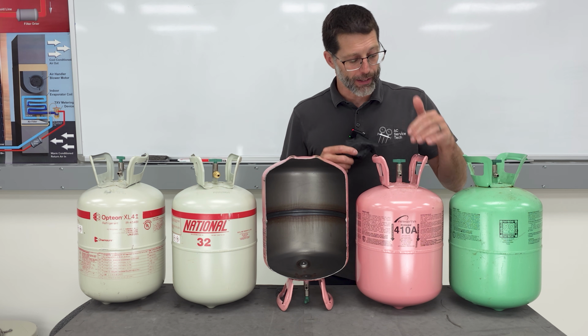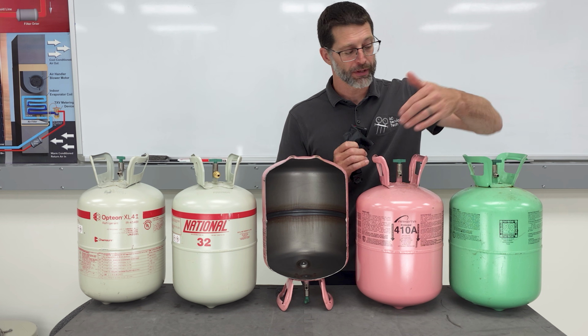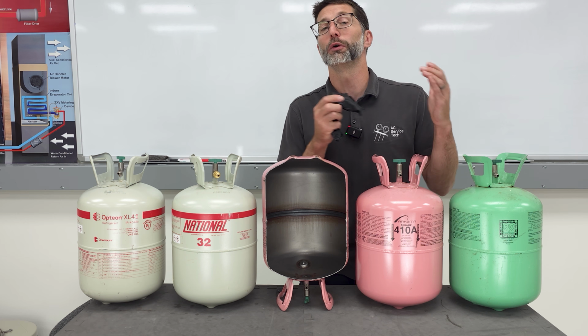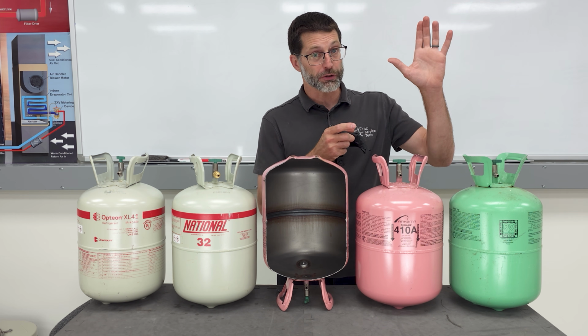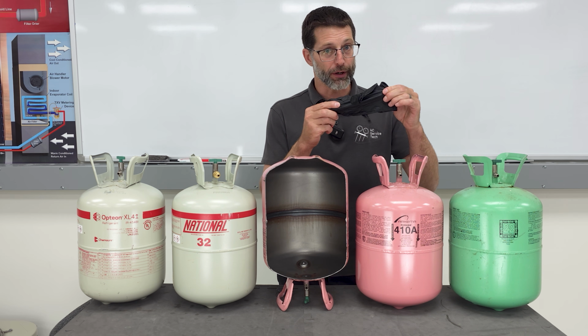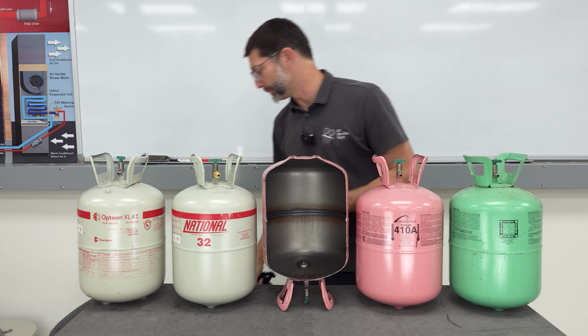As the refrigerant exits the bottle, you've got to think it's at a certain pressure, right? And then it comes out and it's low pressure. So what happens is it flashes, it lowers in temperature. If there's a pressure-temperature correlation and it comes to a low pressure area, it's going to lower in temperature. And so you want to avoid your fingers getting into contact with that low temperature refrigerant exiting the bottle.